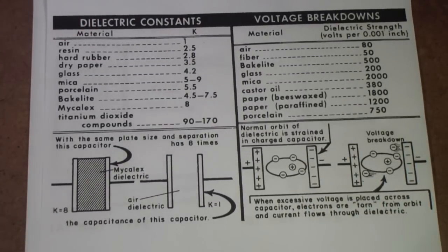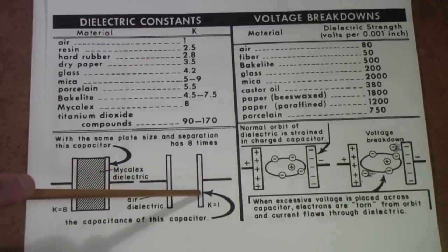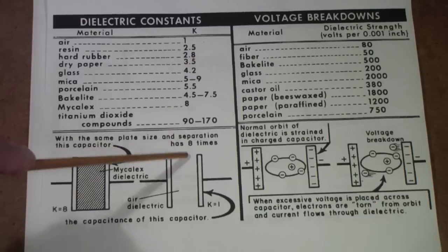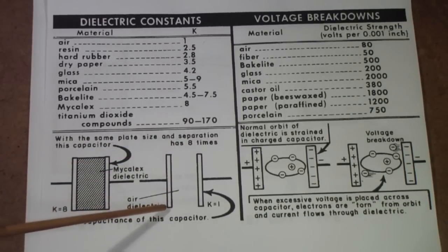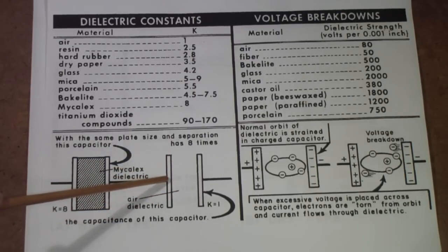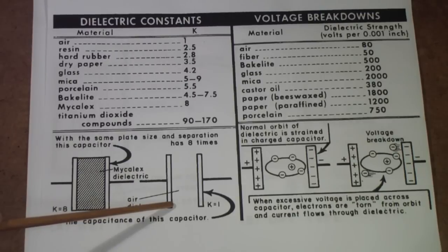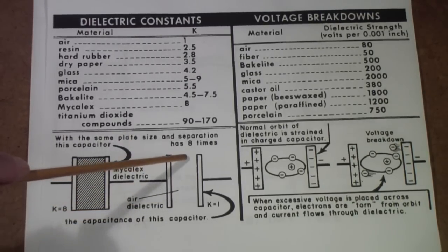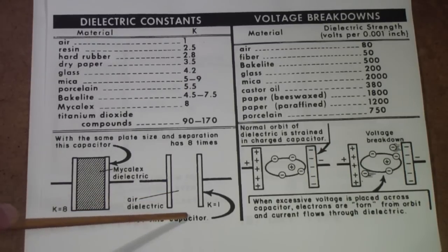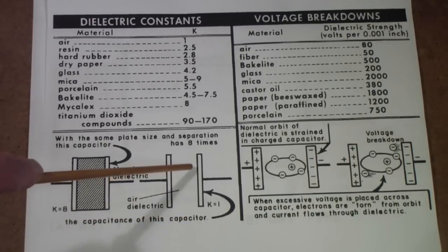Now let's close by just talking a little bit about capacitor theory. A capacitor is basically two metal plates, or two conductors I should say, separated by an insulator. The capacity depends on three things: the size of the plate, the spacing of the plates. So the bigger the plate, the higher the capacity. The smaller the spacing, the higher the capacity. And finally, the insulator in the middle, which is often called the dielectric. And different materials make different capacities.